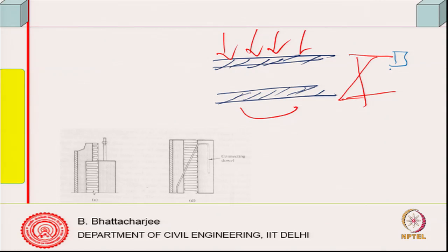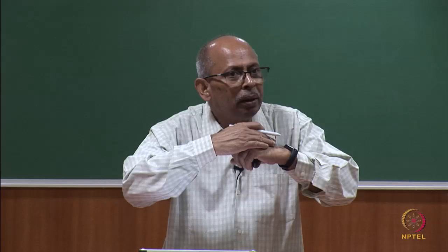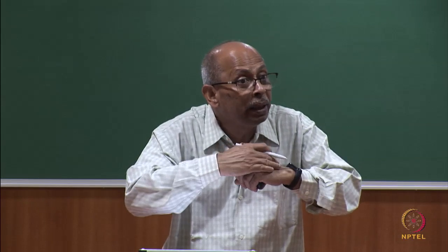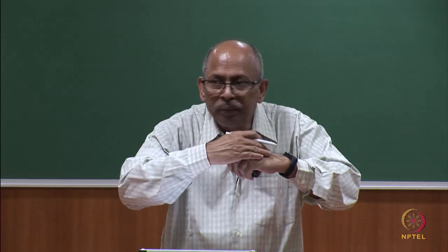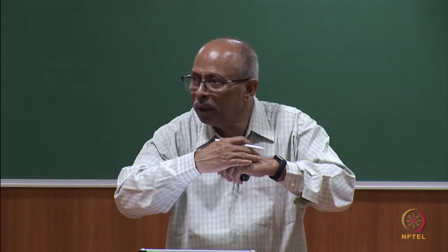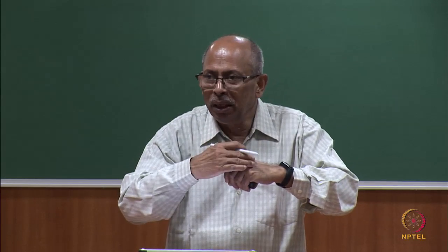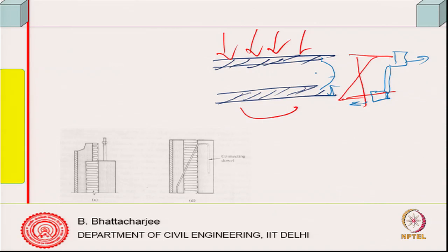I can neglect this portion. So, this is, let us say, tension and this is compression. So, this zone, I can just simply neglect their effect, they are only causing shear transfer. So, shear diagram, of course, you will have something like this, because the top material will slide over the next layer of material since it is bending. So, that shear force has to be transferred from the top layer to the middle and middle to the bottom, and as we know, bending shear is maximum at the middle.